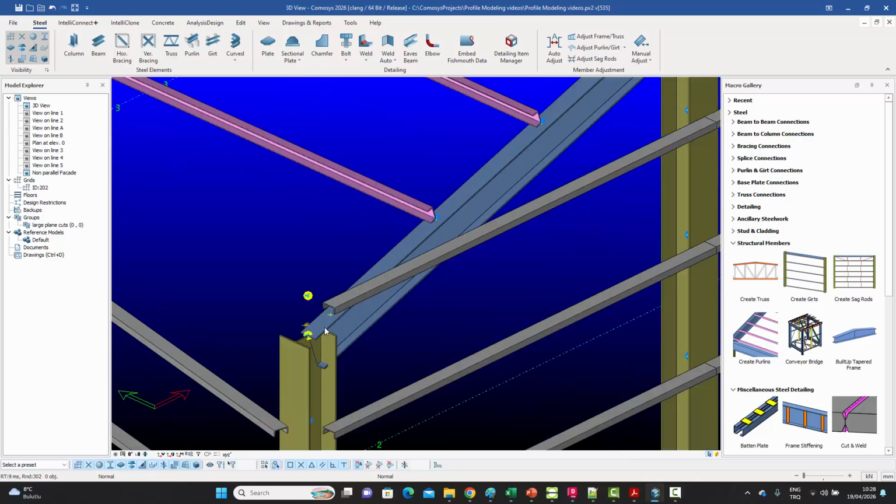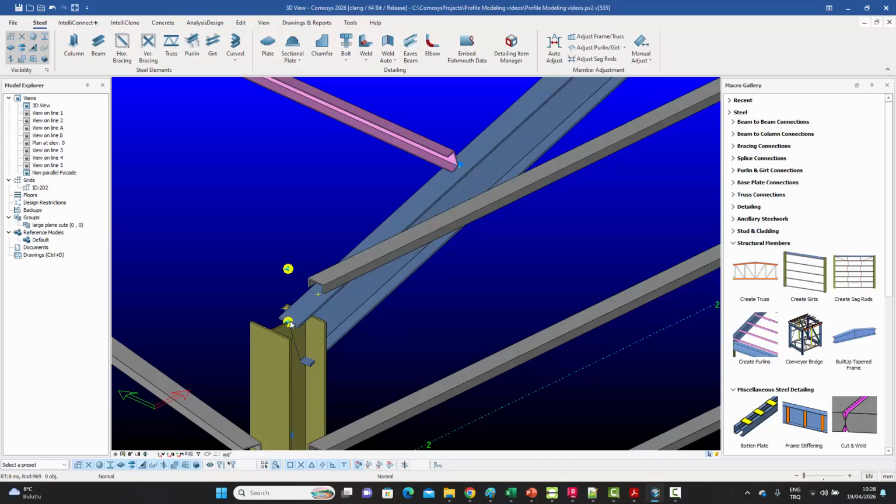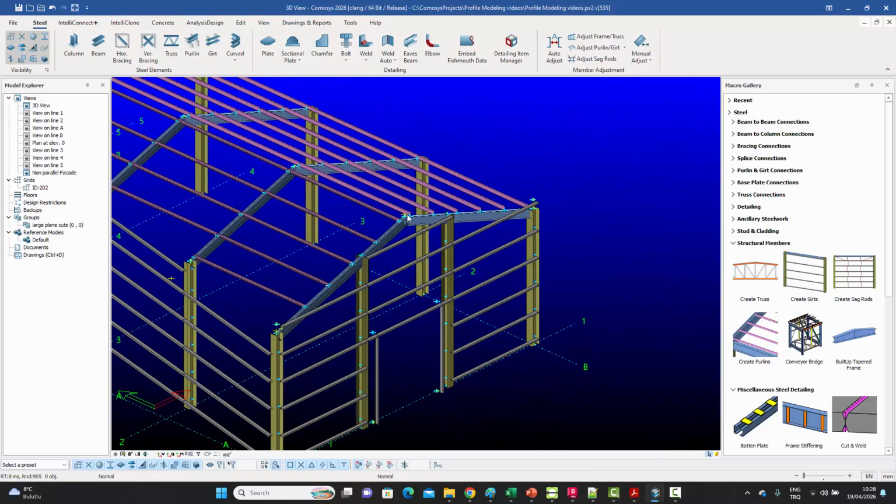And that would be that you create a point slightly elevated. So I've created a point which is at a distance of 100 millimeters in the direction perpendicular to the roof at that point. And we use those points so that we don't have an overlap with the roof beam.